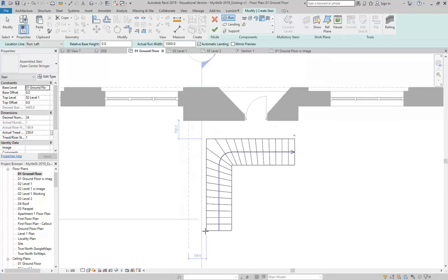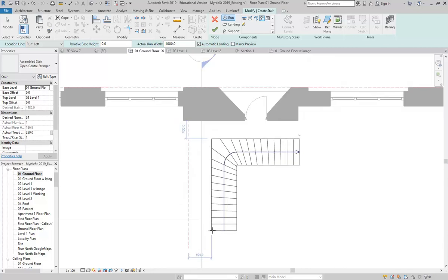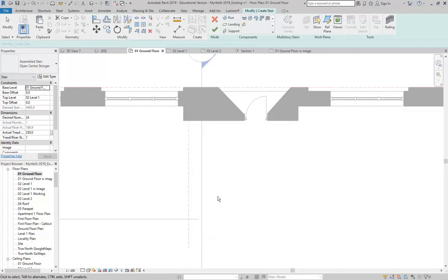Exactly, the angled treads, that's right. That's not correct. For an L-shaped stair, you don't want the winder to start at the beginning. And that's what's happening there. So you can just avoid those tools. The L-shape and the U-shape at the end, don't use those. But the other three at the beginning, they're all good. So we've got straight, full step spiral and the curved or centre end spiral.